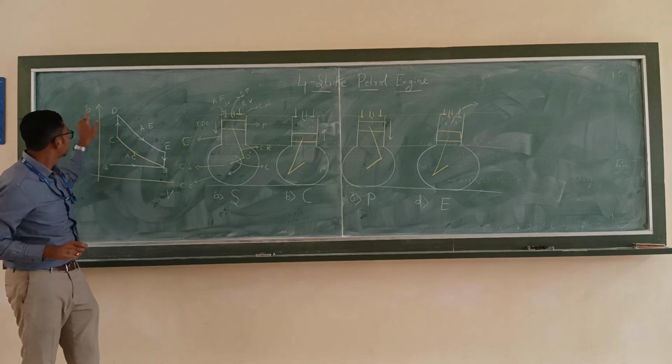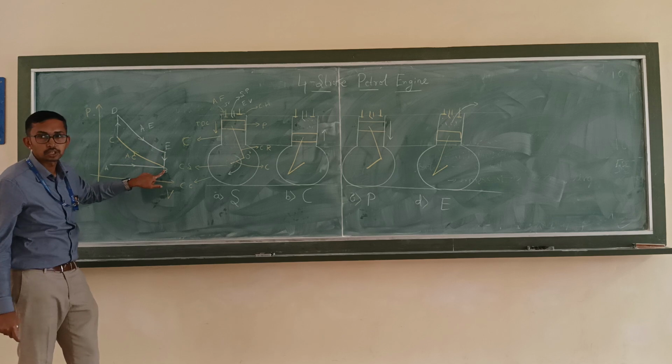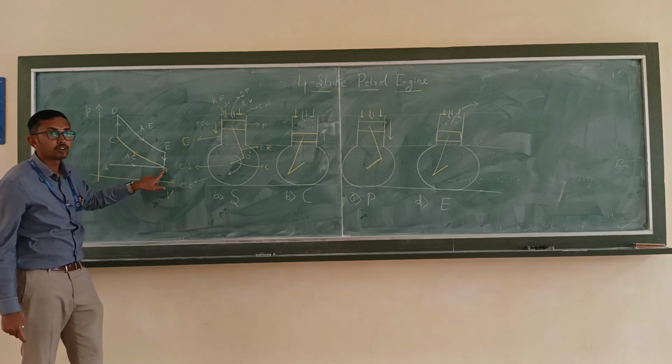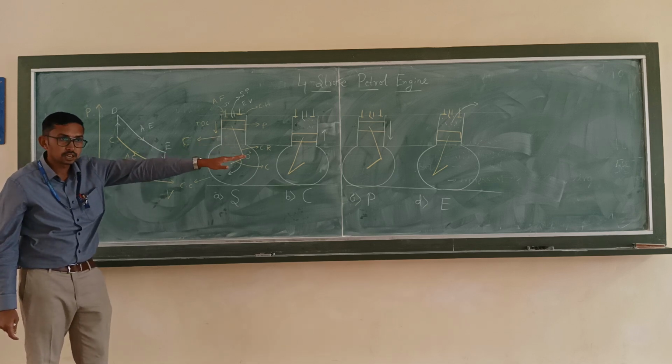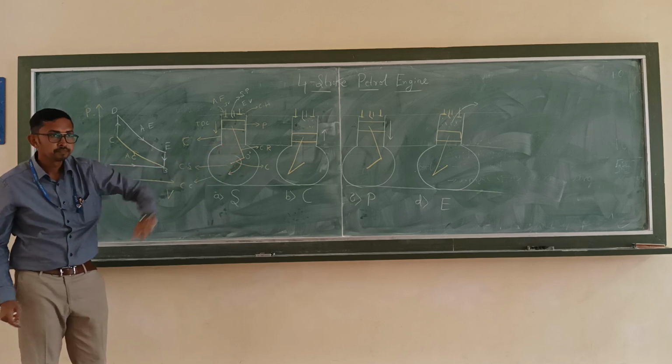Okay. So there will be a drop in pressure due to the opening of the exhaust valve. There will be a drop in pressure, and there is no change in the volume. Why? Because the piston is still at the bottom dead center only. There is no change.